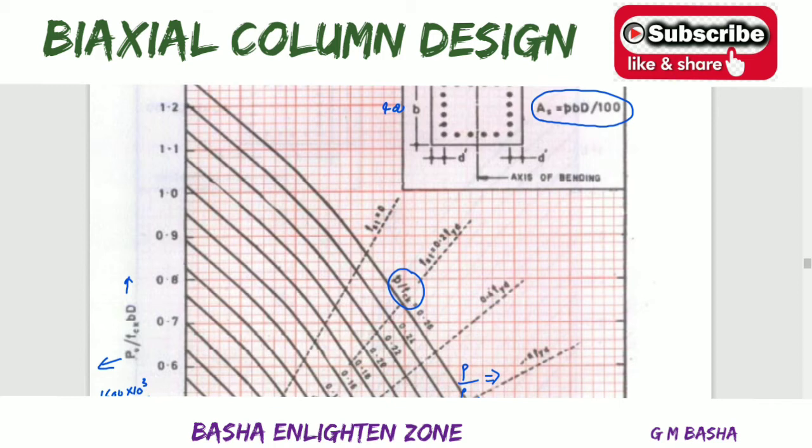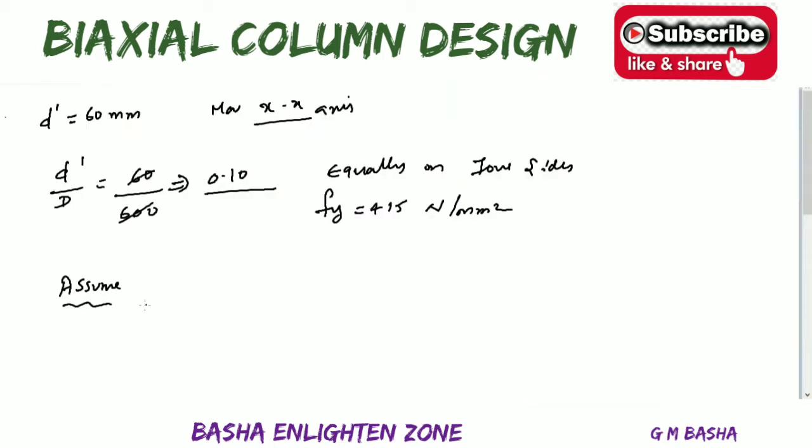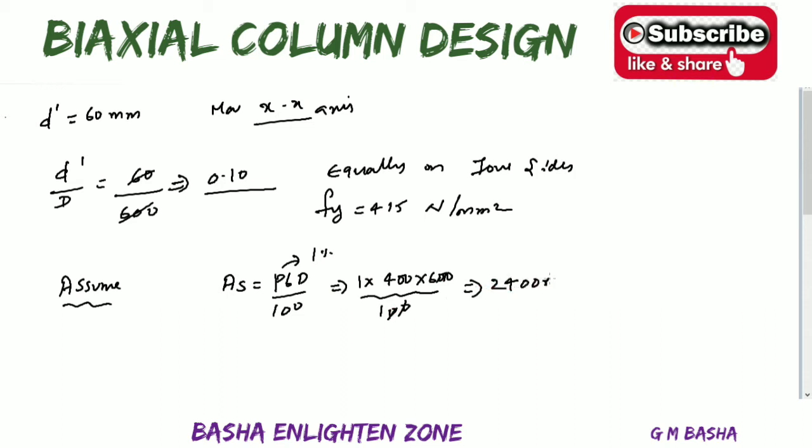I will show here. Your formula is As equal to pbd by 100. Here adopt 1% of reinforcement, where p equal to 1, like 1 into 400 by 600 divided by 100. If you simplify this, you will get around 2400 mm square. For that, please provide the dia bars.